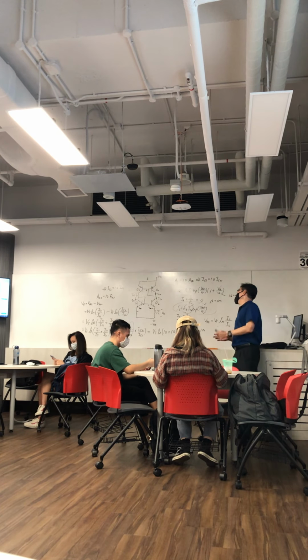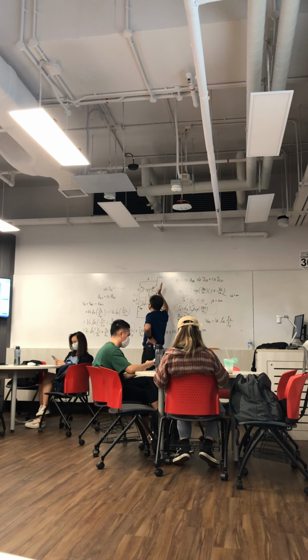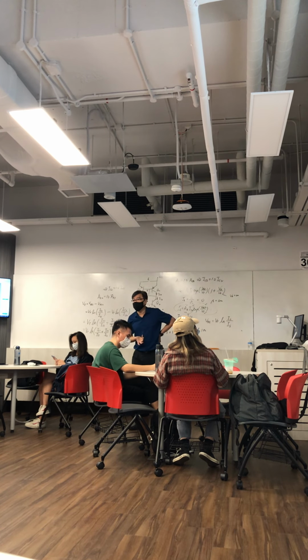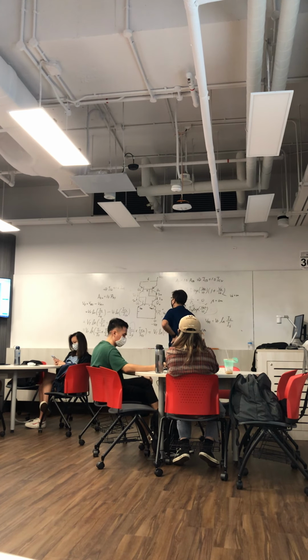So basically, the key point is because these two phase emitter voltages are the same, that causes the current here to depend on the emitter area ratio. So if this emitter area is 10 times this, then this current will be 10 times this. But not for this case here, because the two VBE are not the same, because there's a resistor there. So that's why there's no contradiction just now, otherwise there will be a contradiction. Even though the area is the opposite ratio, it doesn't cause a contradiction.